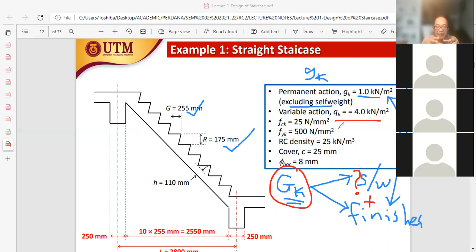Looking at the extreme end, if we say that for emergencies everybody will be using the staircase at the same time, then from 2.5 normal floor slab loading for office, for the staircase in the office building I'm using 3.5 or I'm using 3.0. Okay, and there is always a justification there. We justify. If anyone asks, there is a justification why the QK is selected to be a certain value for staircases only. For staircases. Alright.